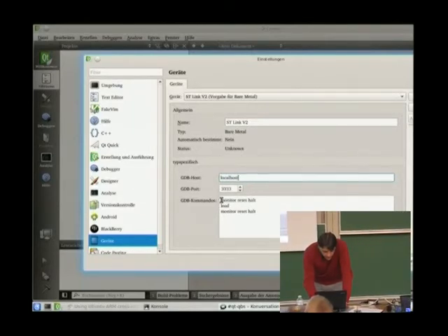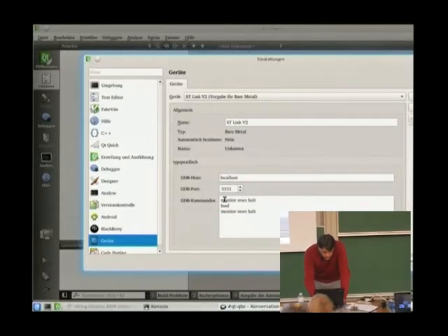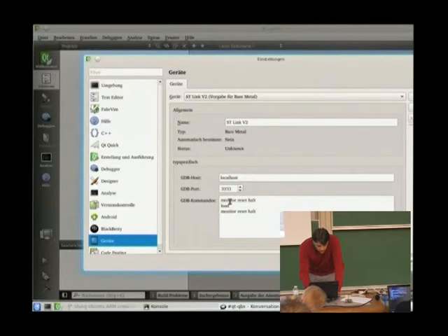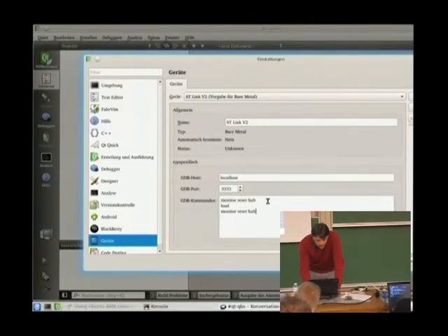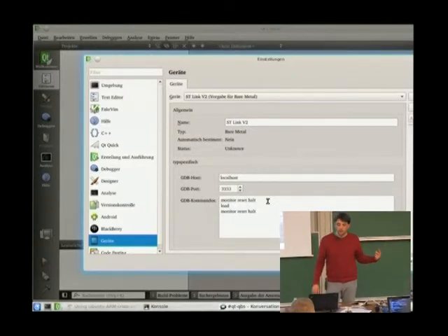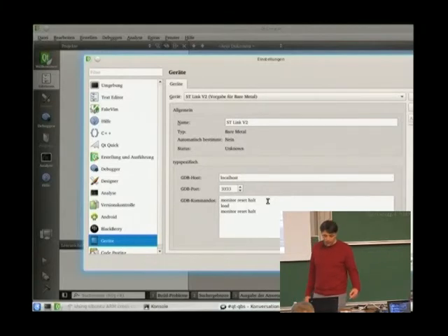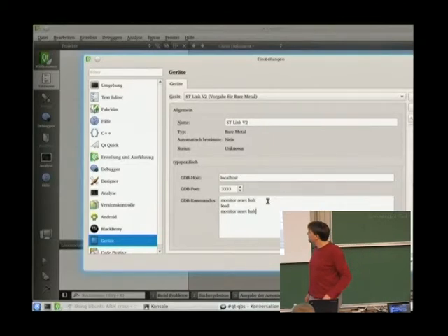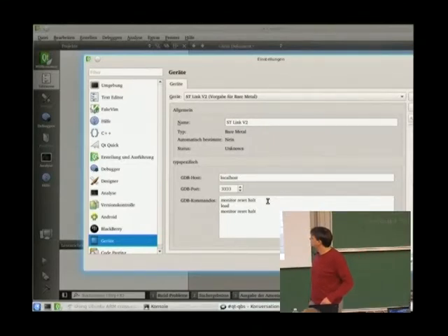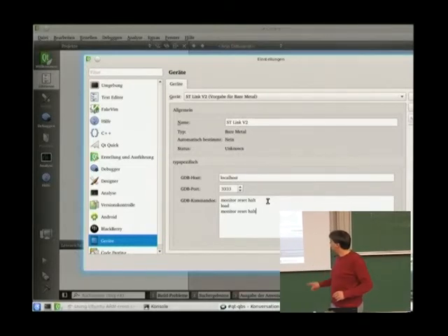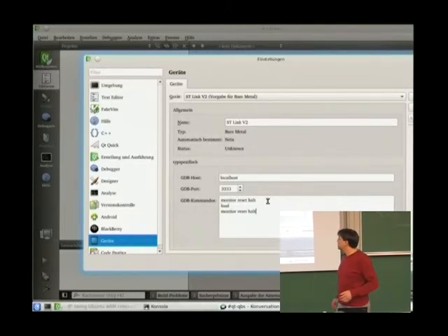So down here are the commands for OpenOCD. Typical commands to get the program loaded are to reset the device, load up the binary into the hardware, and just do a reset again to make sure that it's in a proper state after loading. Normally it's not needed, but that's all you need for getting the device programmed and up and running on this side.